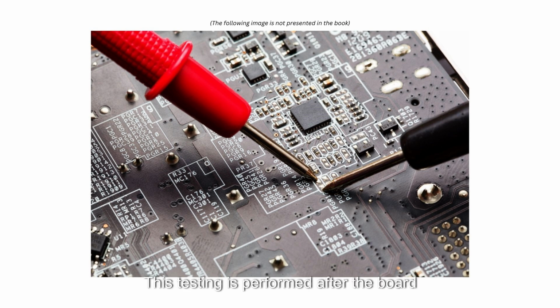This testing is performed after the board has been tested in an isolated state to ensure that it will not electrically damage the rest of the system. Board functional testing is the act of stimulating the board using the peripheral connectors. It is treated as a black box, meaning that the test is simply determining if the output received correlates to the inputs being provided. Those who are testing may not know anything about the circuit, nor are they always privy to that information. In this situation, custom hardware may be needed to provide signals for certain tests.